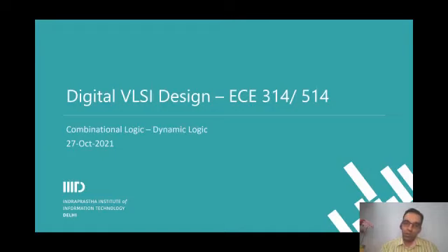The PMOS will go off when the clock goes high, and you will end up with a floating output. At that point, you are dependent on the charge stored on that floating output to ensure that you are stable and robust. That is why it is called dynamic.